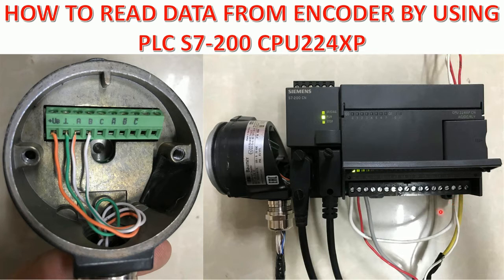For the encoder A and B connection, we connect to I 0.0 and I 0.1. And if you would like to reset the counter, we can connect I 0.2. So that is the connection of the encoder and the PLC S7-200.